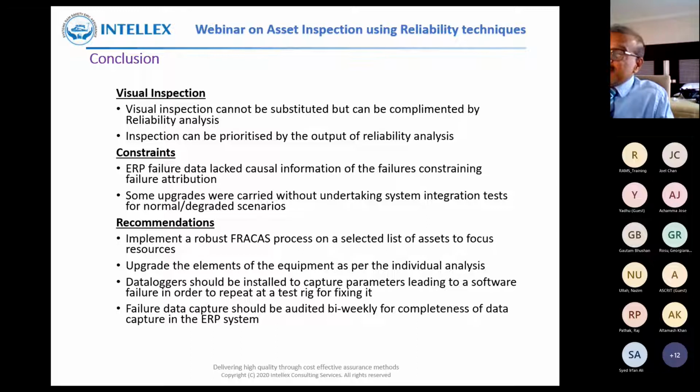One particular thing we found in the control system is software failure. When the software failure happens, the maintainers just come and reset it. Obviously, when you reset it, the software failure goes away, but it is not managed, so it comes back again. For the control systems, because the software failures are not root cause analyzed, they appear again and again. Resetting is not a solution. It only temporarily removes the current environmental parameters, and those environmental parameters would come back again.